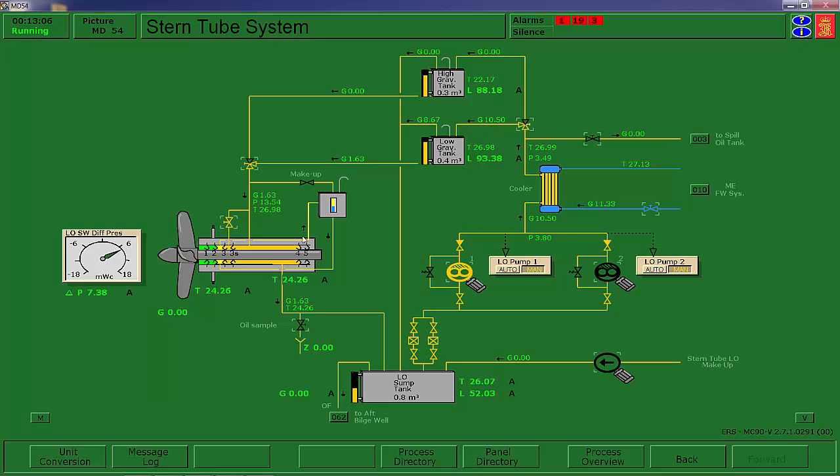When you notice the graphics here, that is feeding on this aftermost space between these. You have two lip seals, 1 and 2, to prevent salt water coming in, and 2 lip seals preventing oil going the opposite direction. And notice they're facing different directions. This little gravity tank is filling that space in between.